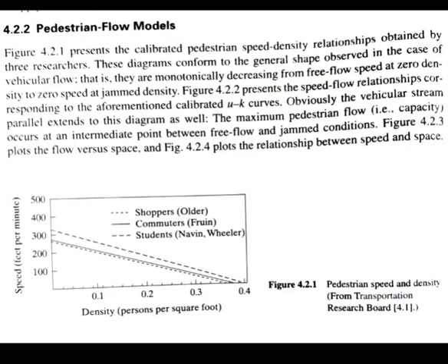Then if it is the worst, that means a road where you have to stop frequently, and the time taken will be very large, and you will be very unhappy to use such a road. So such a section we will give the letter F. F means the worst, and this is based on the range of values for a specific measure of effectiveness. So this is actually calculated based on the density for freeways and delay for intersections.